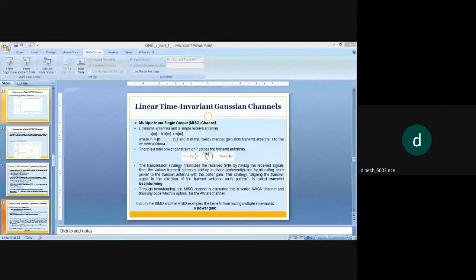So if there are Nc subcarriers, depending upon the chip rate, the largest reliable communication rate with independent coding would be C/Nc bits per OFDM symbol, or bits per second per hertz, as Nc tends to infinity. So the capacity of this frequency selective channel will be C equals integral 0 to W of log of 1 plus P star of f |h of f| squared by N0 into df, which is bits per second.